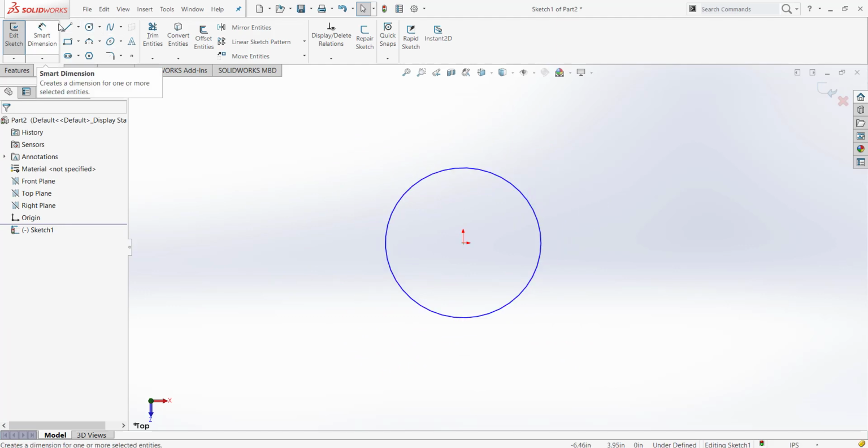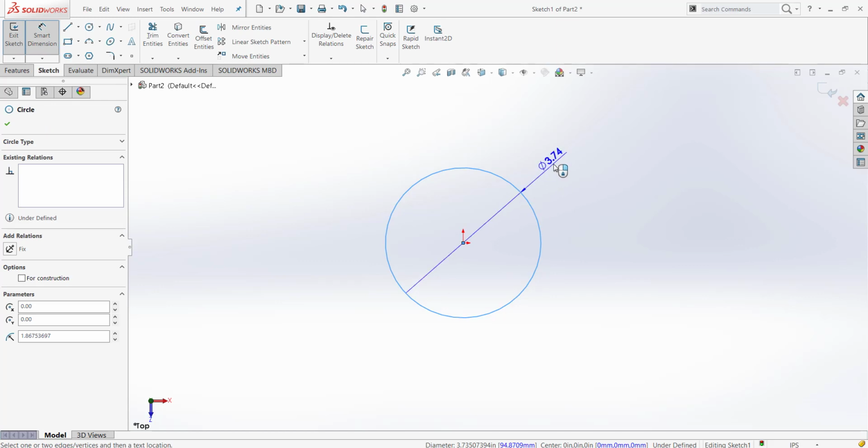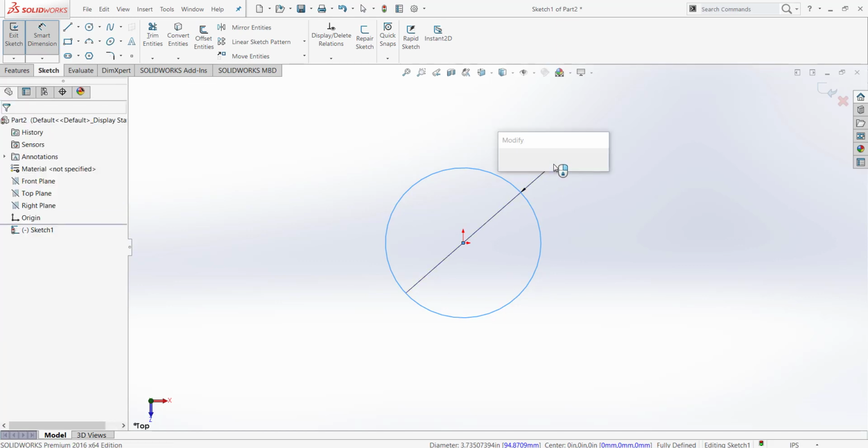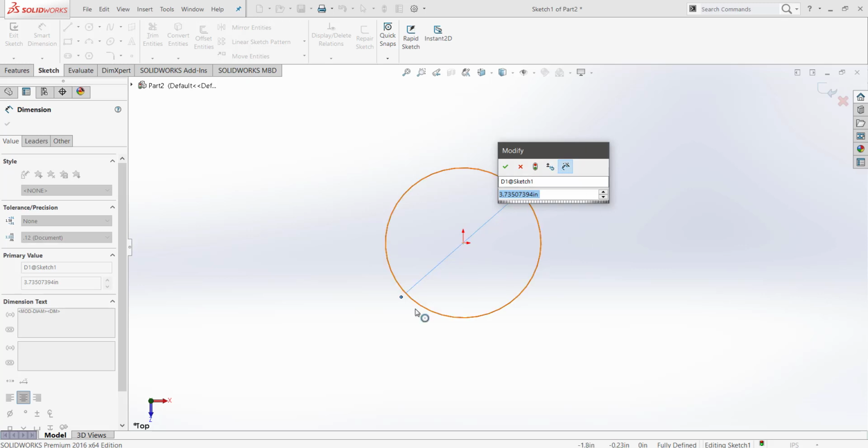So given that I wanted a mug, I'll pick the outer diameter of a mug that I'm thinking to be 3 inches, maybe 4 inches. So I'll say 4 inches. So I selected the arc, and I just use my keyboard and type 4. I can type in IN for inches, but because inches is my default, it would immediately go to 4 inches. If I wanted this to be in millimeters, because my default is inches, I would have to actually type in 4 mm, and that would give me millimeters, but I'm not going to do that. So I'm just going to do 4 inches.